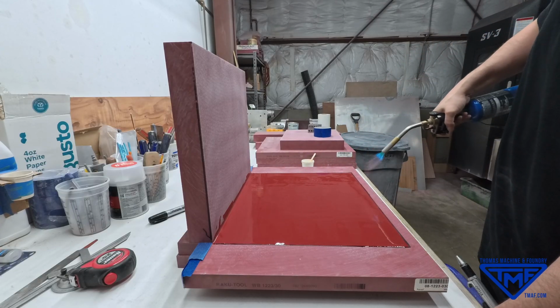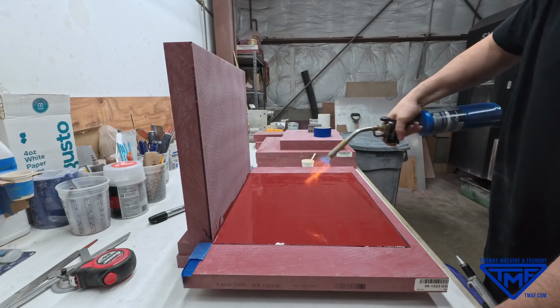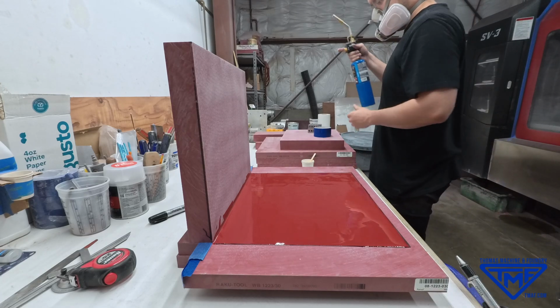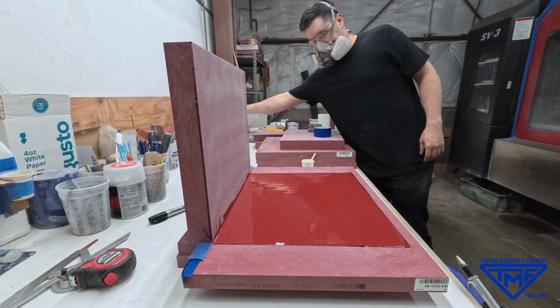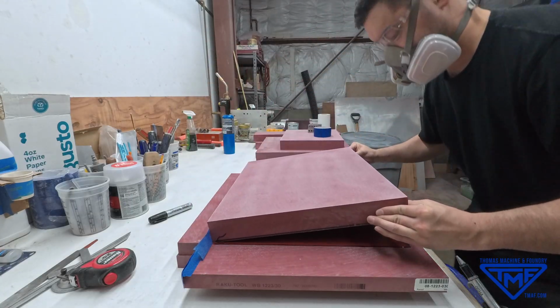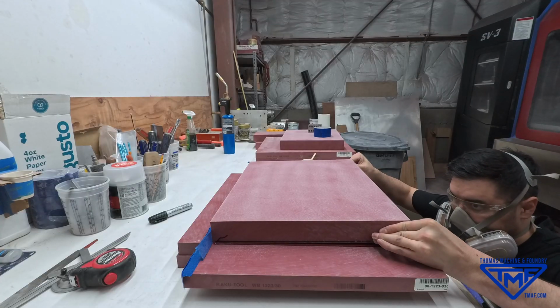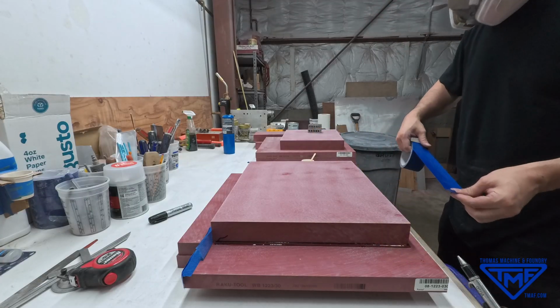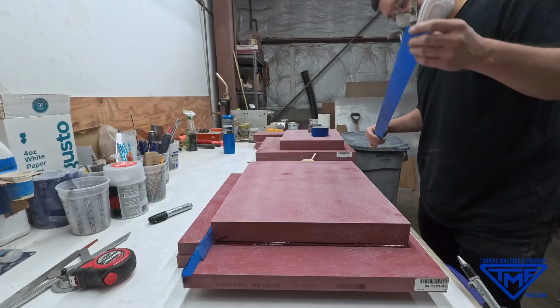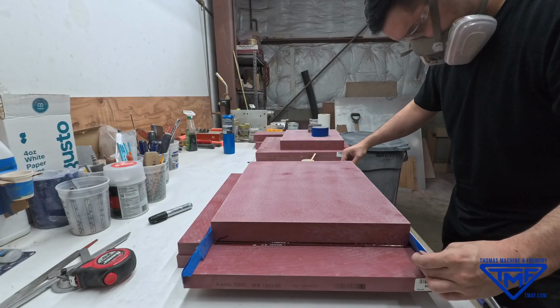These small details matter because the goal is to create one solid, stable block of material. With the epoxy ready, the loose section is carefully lowered into place. The tape acts like a hinge, keeping the piece aligned while we use the layout marks to position it precisely. Additional tape is added around the remaining edges. This keeps the epoxy contained and it prevents the piece from shifting while it cures.